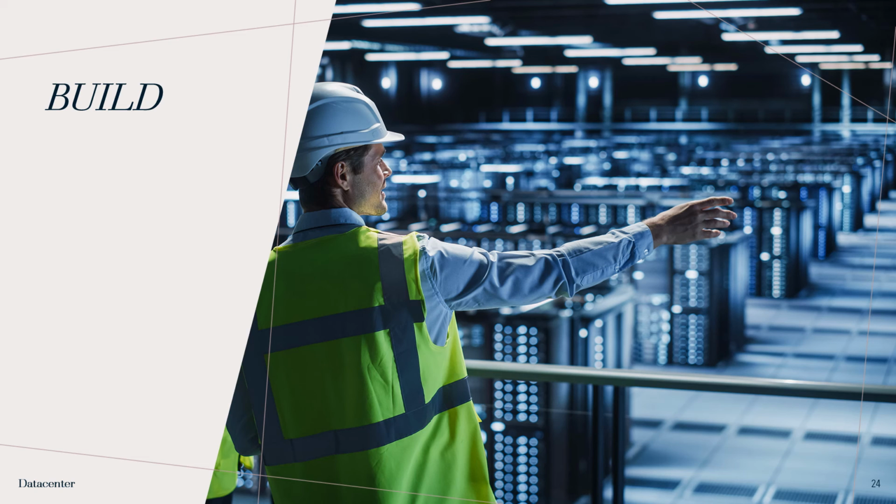Small companies can make do with only one substation, but every machine should be dual powered through two independent routes. Large data centers expected to use more than 2 megawatts can meanwhile switch from the UPS with batteries to unique battery-less power solutions, the so-called dynamic or rotary UPS. These combine a transformer, a UPS and a motor generator in one pack. It works a bit like a flywheel in a vacuum case that is spinning endlessly and can convert the stored energy through a generator into critical electric energy when needed.